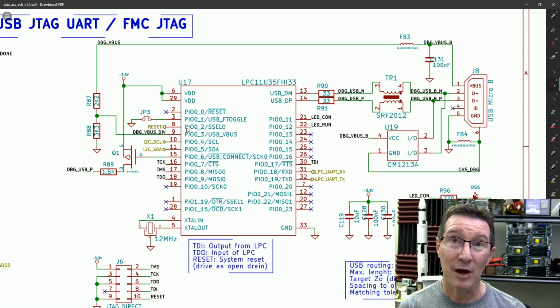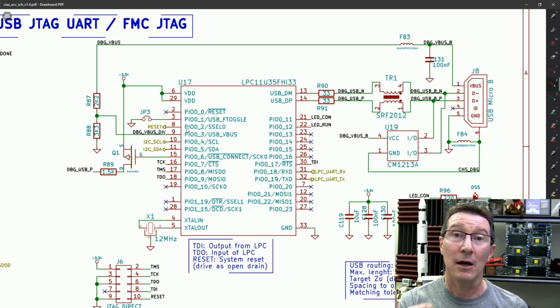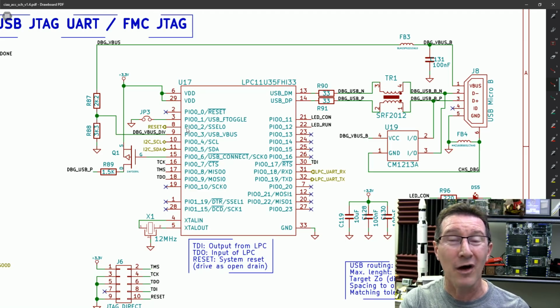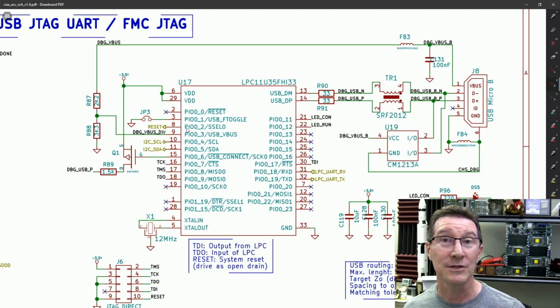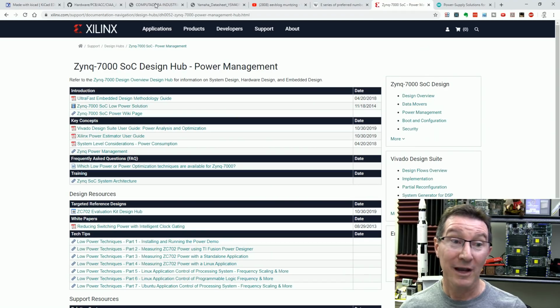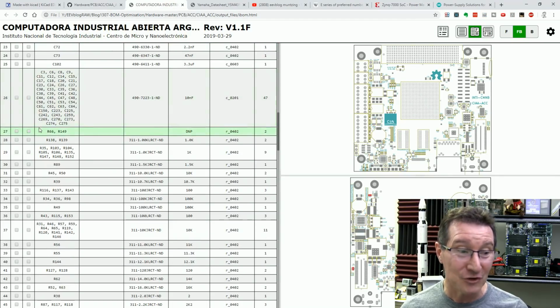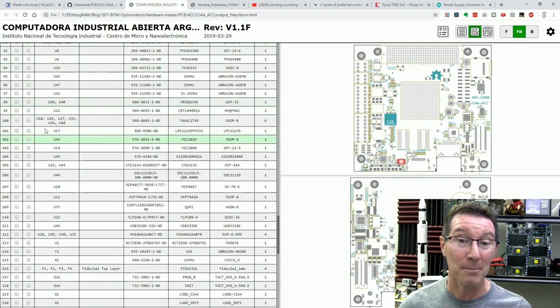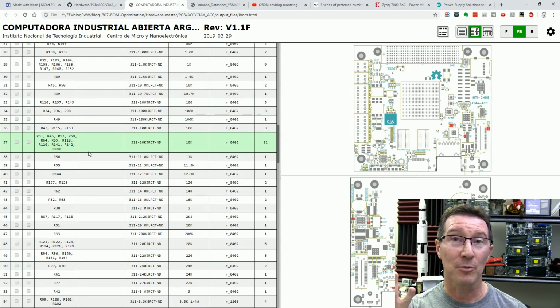Diodes are another classic one, for example, where you might use a 1 amp diode on your input, for some sort of clamping or reverse protection, and then you might need another diode in your design. Do you actually need that to be a 1N914 or some other signal diode? Can you actually reuse that same power diode? Try and consolidate your parts and reduce the number of line items on your BOM. Now, the third type of optimization, once again, is another design for manufacturing technique.